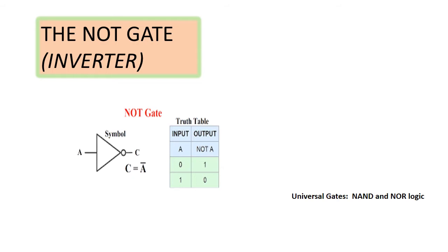Though logic circuits of any complexity can be realized by using only the three basic gates, which are AND, OR and NOT, there are two universal gates also, and those are called NAND and NOR, each of which also can realize logic circuits single-handedly. So the NAND and NOR gates are therefore called universal building blocks. Both NAND and NOR gates can perform all the three basic logic functions, that is AND operation, OR operation and NOT operation.